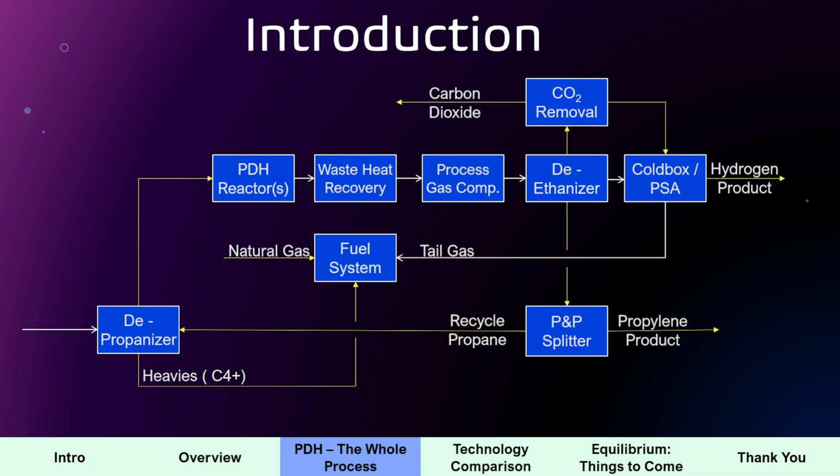You need to purify your propylene to almost 99.9+% by weight, and that's what the specs of the propylene product have to be if it's going to be used as a polymer grade, which the majority of propylene is used for. If we're talking about a polymer grade, it's going to be 99+%. If it's a chemical grade, it's going to be 90 to 95%. If it's a refinery grade product, it's going to be 70% to 90%.